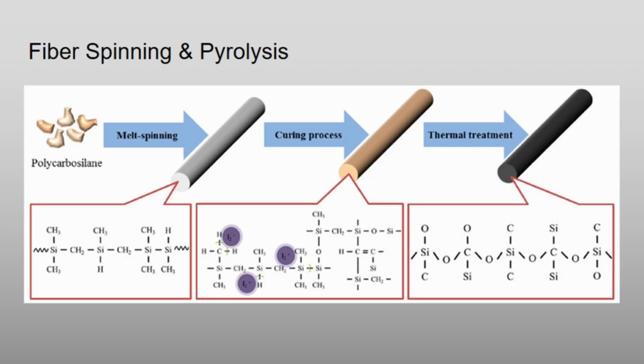Separate silicon-based polymer fibers are spun, cured, and pyrolyzed at high temperatures to create continuous high-strength silicon carbide structural fibers. This diagram details the initial step growth extrusion of raw preceramic polymer melt streams into fine filament bundles, followed by low-temperature air vapor cross-linking to build an infusible network shell.